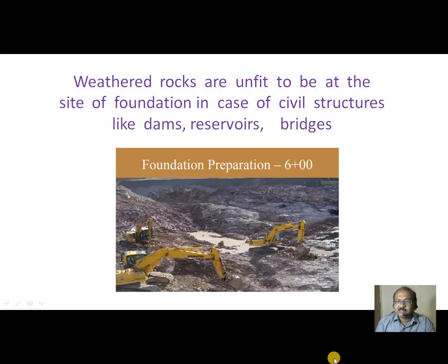Weathered rocks are usually unfit at the foundation in case of civil engineering structures like dams, reservoirs, bridges. So, foundation part is very, very important. If the rocks are weathered, that site is unfit for foundation purpose.